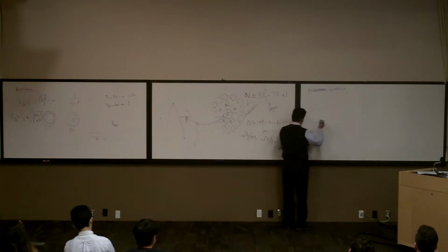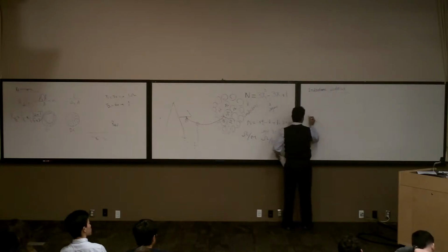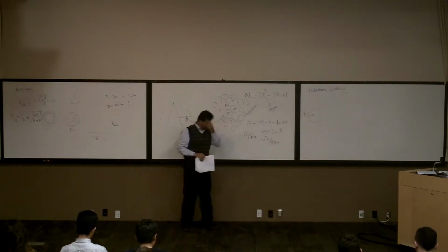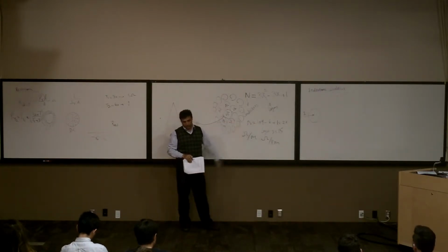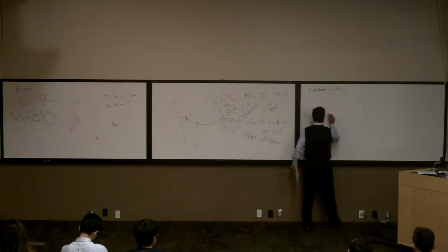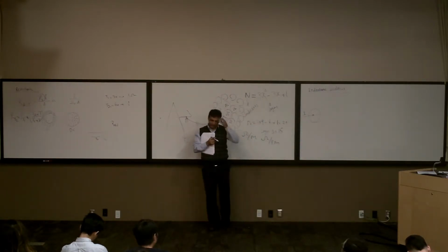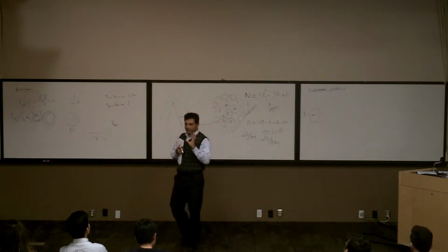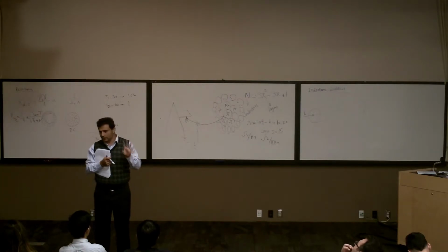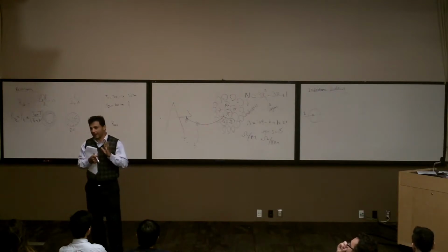Let's say the current is I. Let's say the current I is going here. Now we want to calculate the inductance of this wire. Let's assume this is the center. So there are two inductances. And we know from what I said, inductance is a result of flux. Whenever we have a flux lambda, the inductance is lambda over I. So wherever we have a flux or lambda, we're going to have inductance.